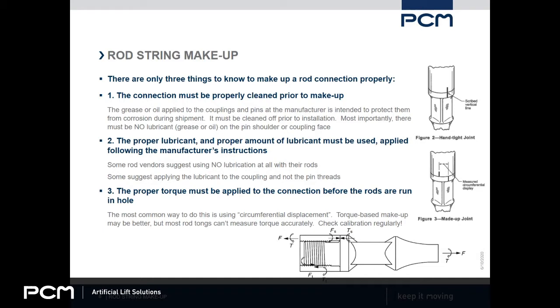Calibration cards need to be appropriate for the application. They need to be for the right rod. If you're running PCP rods, you need different cards than if you're running beam pumps. If you're running a standard API rod that's actually designed for beam pumps, you should be putting more makeup in than what the recommended practice says. So they should have a card for that as well.